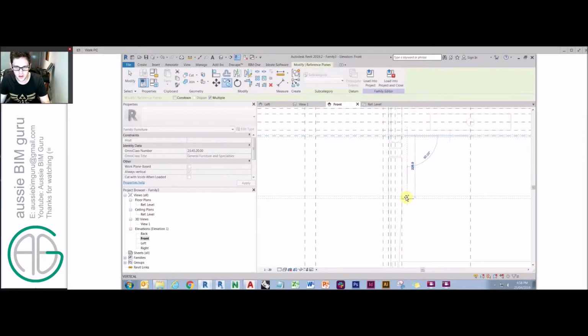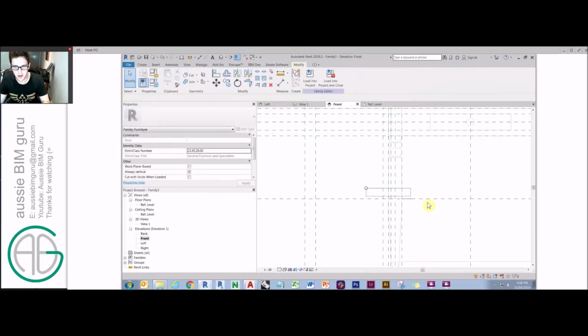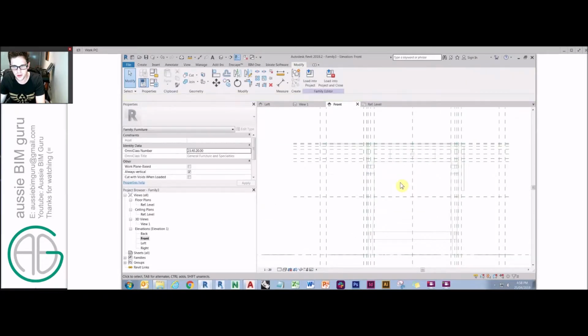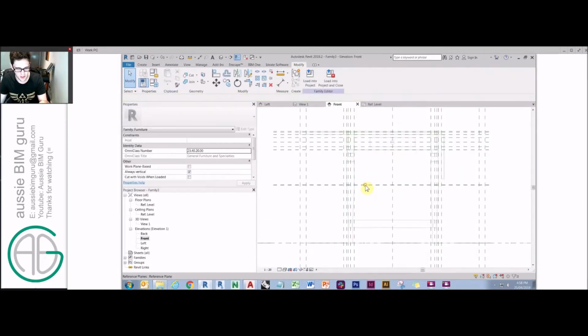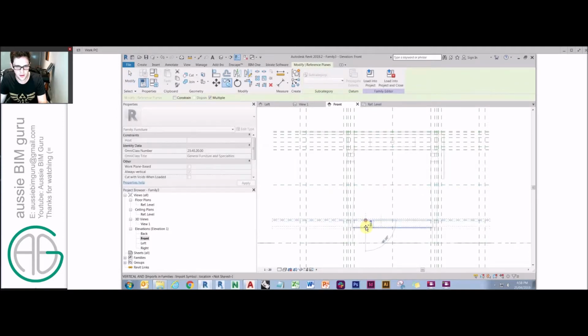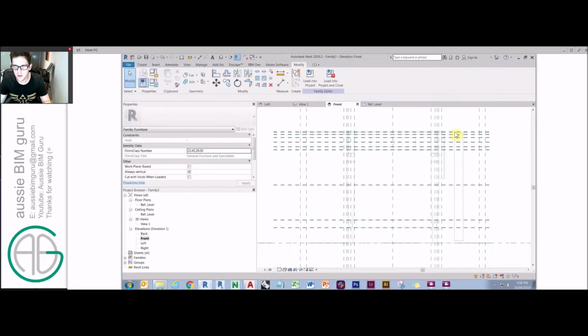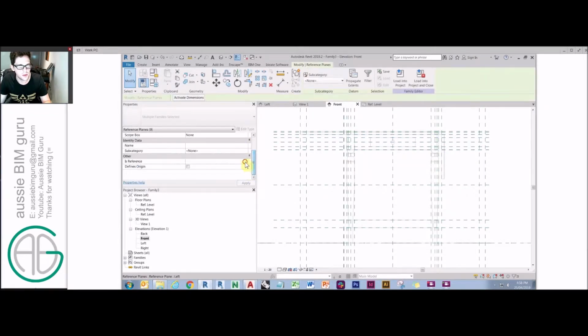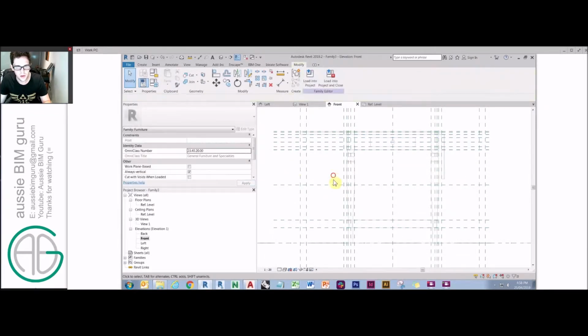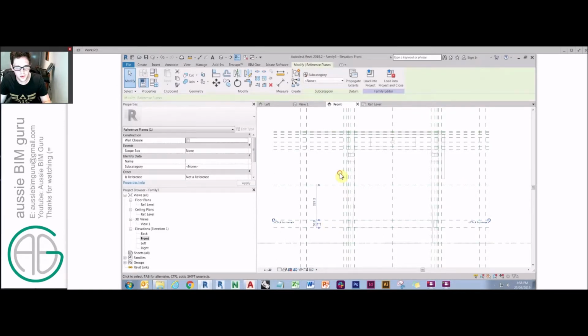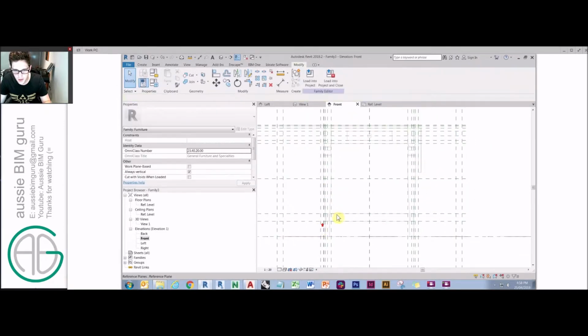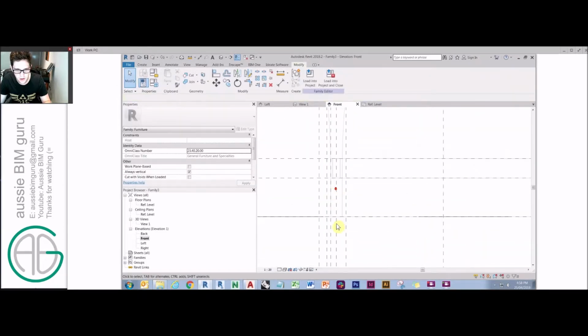And some of these things I'm setting up with the intent of making this family parametric later. So you remember this is our growth zone where our family will be able to get larger in size. And then we'll copy these down here. And likewise, we can take all these planes and make them "not a reference" as well. There we go. And I think beyond that, we just need some planes for these.